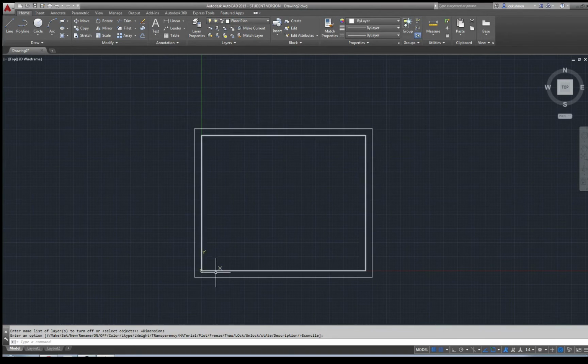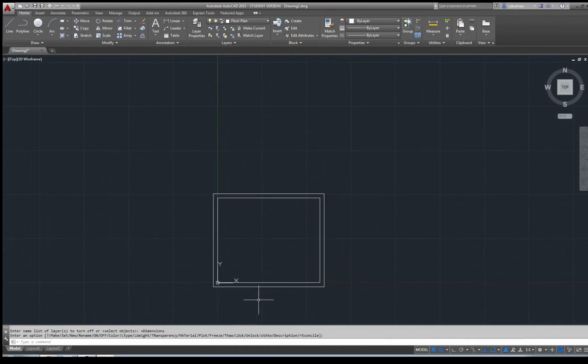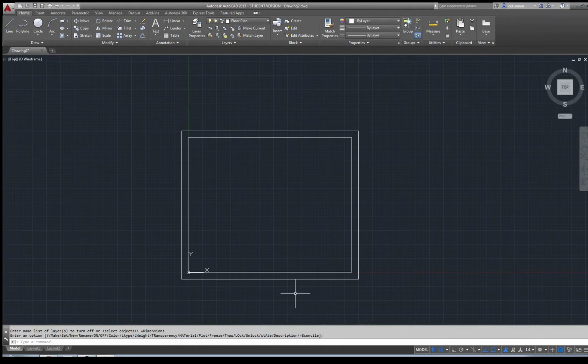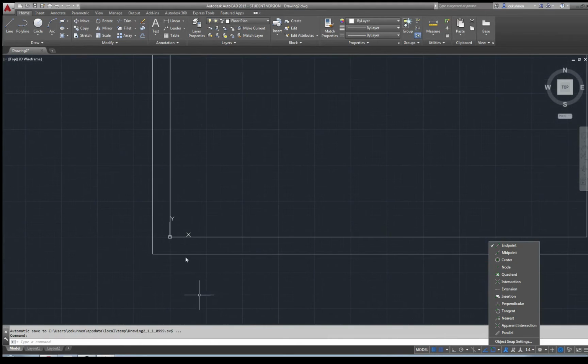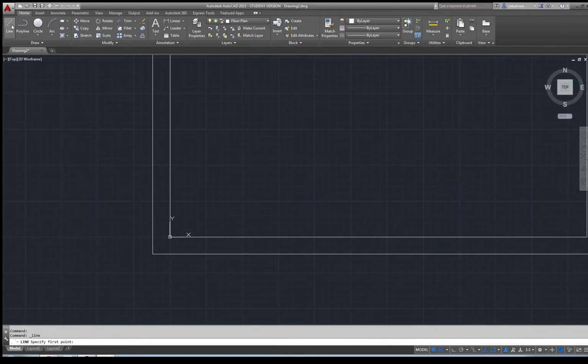Okay, at this point, let's go ahead and create some more information for my room. I have, for example, in the lower left corner, a small door. And let me show you different ways how, for example, we can create it. And specifically, we're going to use the snap tools really a lot. So from this corner to here, 13 inches, that is actually where my door starts. There are multiple ways how I could do this. One way, for example, would be I create a line, snap to here,